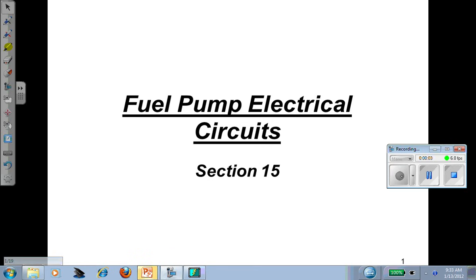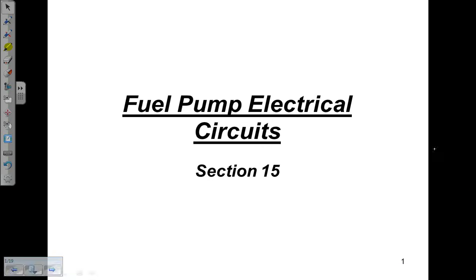Section 15, fuel pump electrical circuits. First thing you want to understand with fuel pumps, computer-controlled fuel pump circuits, and this is the majority of them, work this way. You have a computer that controls a pump relay. That fuel pump relay is going to control the fuel pump. This is based on two inputs.